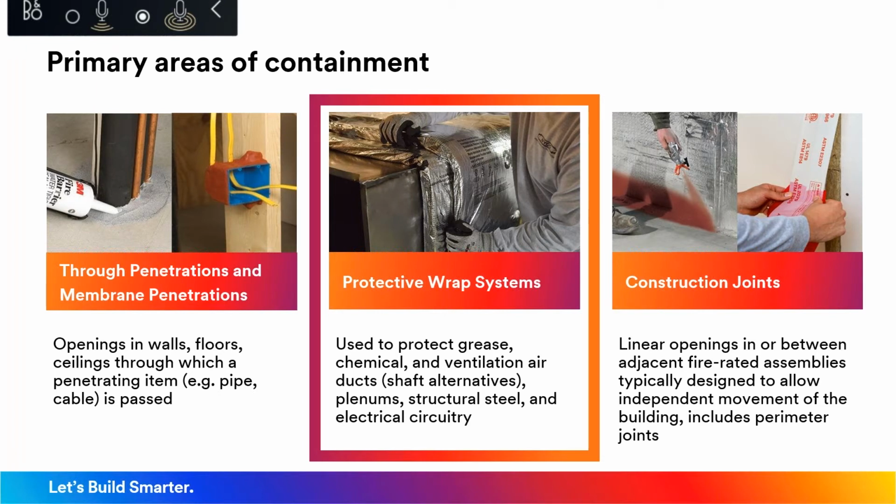So we want to make sure that if the system identifies a certain amount of compression of mineral wool, certain amount of compression of those pillows, certain depth of putty, if it's a device, like a pass-through type device, that requires it to be installed in a certain manner, we want to make sure that we follow those UL systems to a T. Otherwise, just something as simple as that hose stream hitting the materials is going to cause a failure.